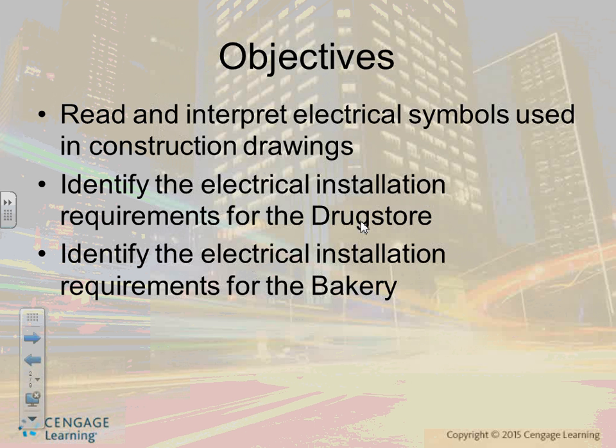So when you put your fixtures, guys, first we drop it, and then we go look at it in the side view to see how it looks. I'll show you how to do this in Revit. Yes, sir, you can set a different height in the properties. Do you drop everything on center, like maybe 8.5 feet on center? Typically on center. It's easier because then you don't have to worry about how big the fixture is.